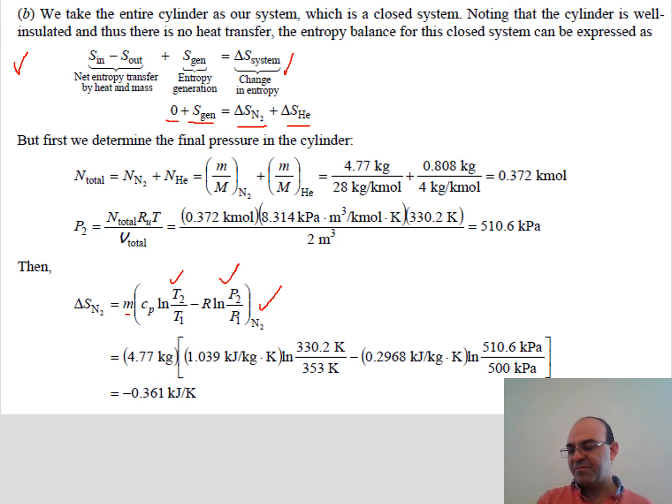One is that you write the ideal gas law for each of these two gases for the final state 2. So meaning that you write P2V2 equal to mRT for each gas, and then in this equation you wouldn't know the volume. Volume would be unknown, final volume, and also the pressure would be unknown as well.